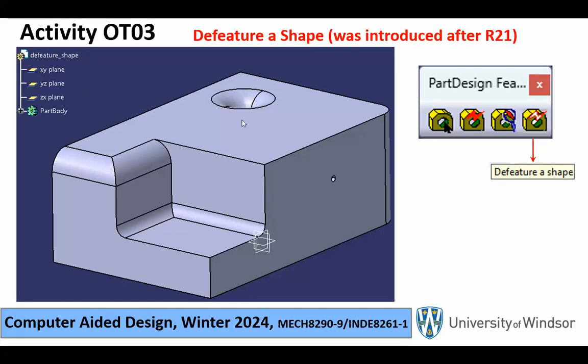Make something like that. I'll put some fillet radii, or rounds basically, of 10 millimeter. These are 3 millimeter fillets. And then I have a hole here with a diameter of 10 and a hole with a diameter of 5 or something like that.